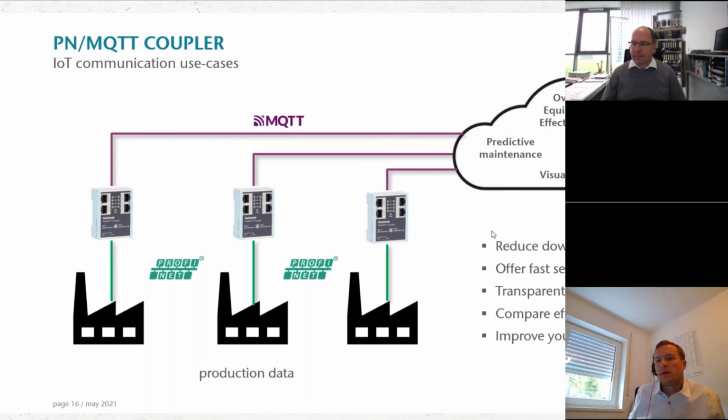All right. Another question that came up is, do I have to use the TIA Portal for the configuration of the coupler? No, this is a standard GSDML file. So all PLC manufacturers with engineering tools which can read in the GSDML file can use it. There's nothing obscure inside.